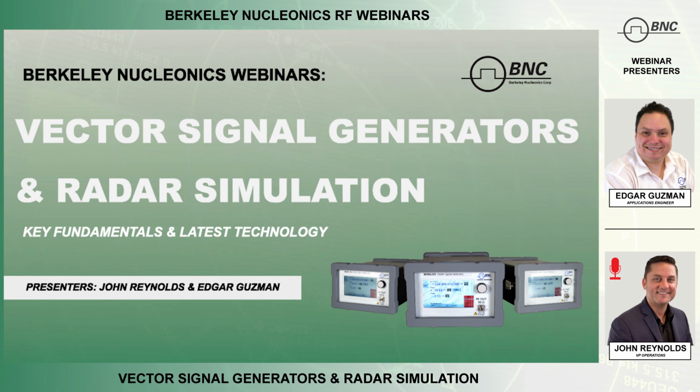This helps to ensure that the radar system is functioning correctly and any issues are identified and resolved before the system is deployed. A vector signal generator provides a realistic simulation environment by generating the necessary signals to simulate the radar system's performance. This includes generating signals that simulate the radar signal's frequency, phase, and amplitude. Phase noise, switching speeds, and modulation capabilities are the most important things when you are selecting a vector signal generator